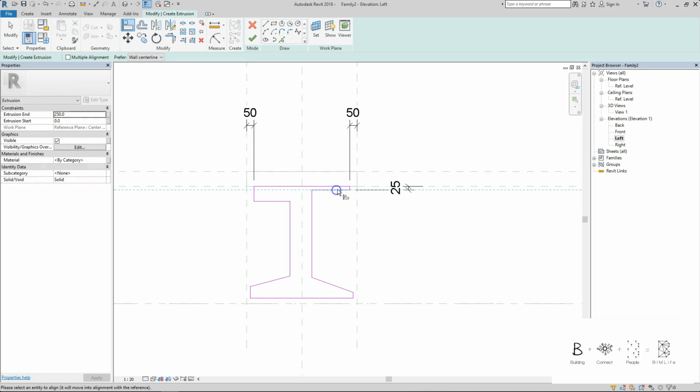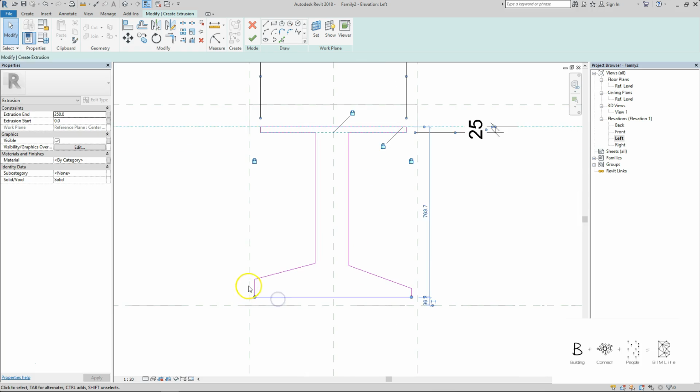I should lock this sketch line to this one, because this line is already locked at 25, so this line can follow the other side. And let me see, what else do I need? And the legs at the bottom of the table are towards the end. Okay, so I'm just going to lock this and lock it to the bottom as well. And same for this side here.